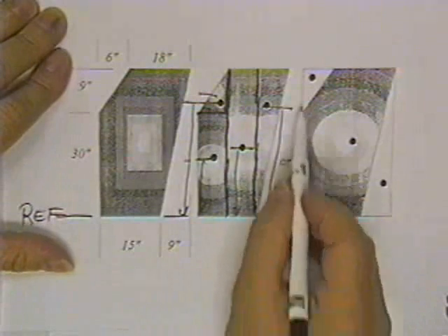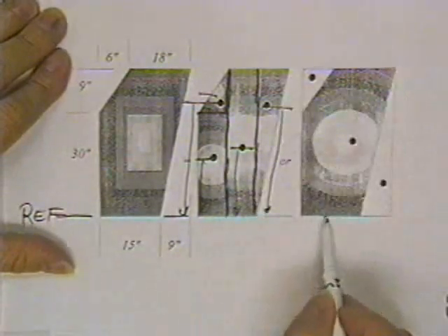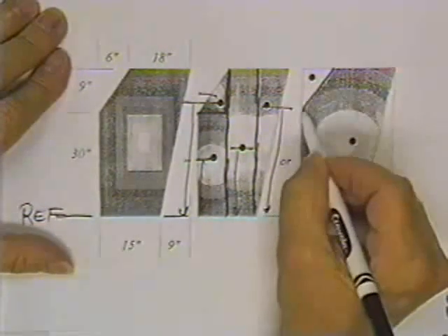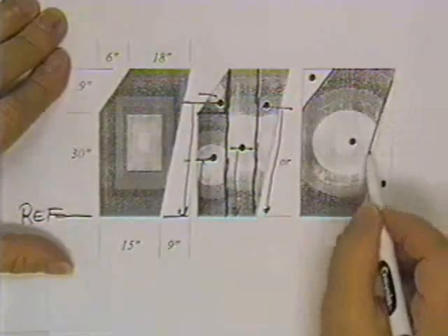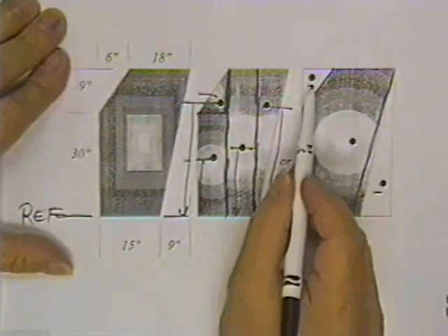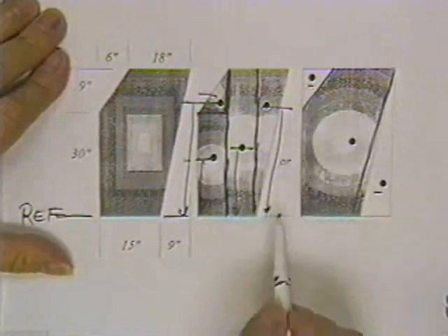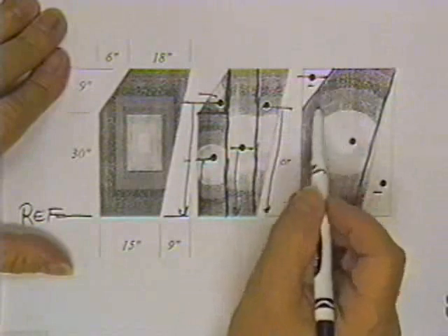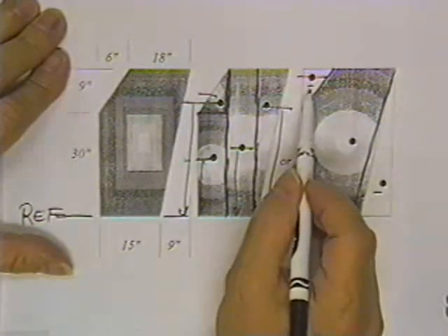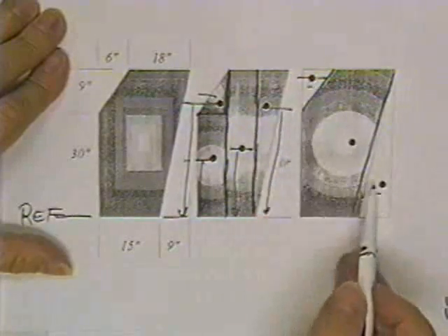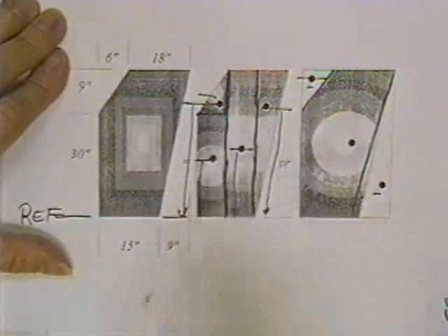You could also pretend that area 1 is a solid piece. The whole thing is solid. And then you subtract this and you subtract this. You make these two minuses in all respects. You put them as minus areas in your centroid equation. You put them as minus moments of inertia about their own axis. You put them as minus moments of inertia for their transfers. That way you'd only have 3 terms instead of 1, 2, 3, 4 terms.